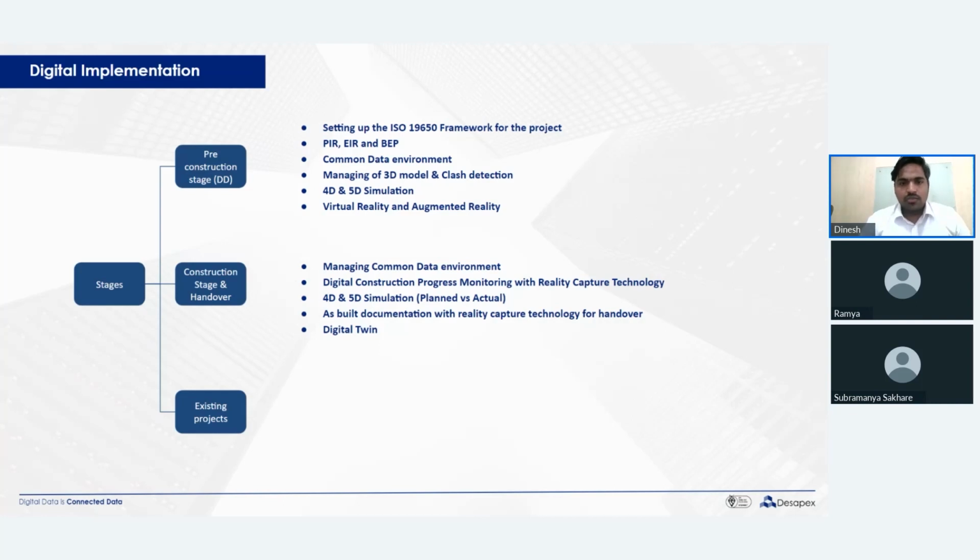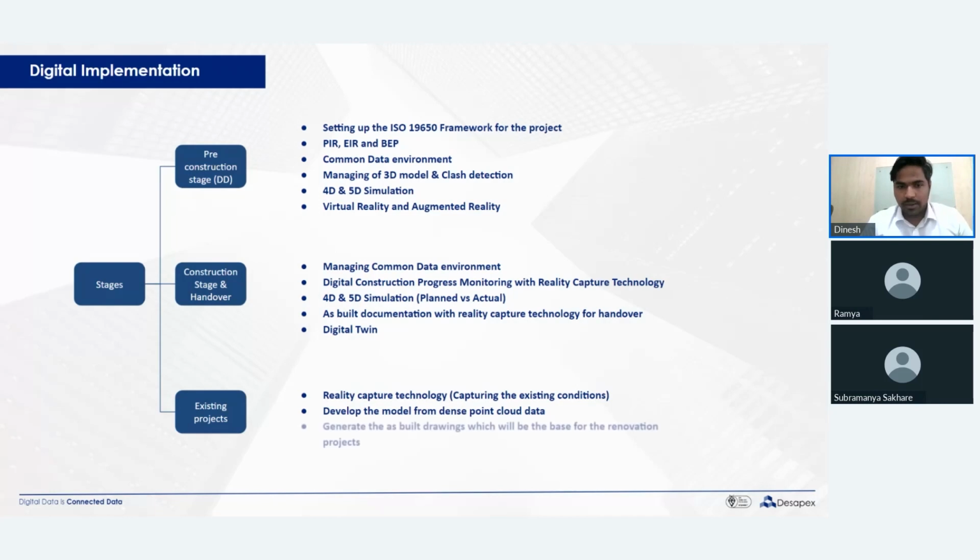So this digital twin is where it will be taken to the next phase. Reality capture is also used for existing buildings in retrofit projects, where you don't have the present as-built drawings, assets, or floor plans. Again, capturing the asset and developing a 3D model from scratch from the point cloud data, you can then generate the drawings for a renovation project.